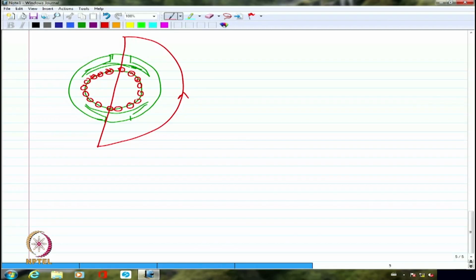Because of which I will have this magnetic field corresponding to the stator passing through the rotor and then completing itself through the yoke. If this is dot and this is cross, I would have had the magnetic field line going up. Now maybe I will have the magnetic field line going down in the case of the rotor as well. So, if the magnetic field line is aligned exactly with that of the stator winding, I am going to say theta is equal to 0.